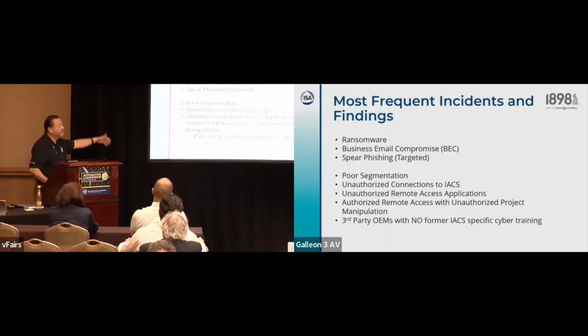So other pieces here, I think we talked about poor segmentation, unauthorized connections, we see that a lot, unauthorized remote access applications. The TeamViewers, the RealVNCs, the UltraVNCs, the RAdmin, there are so many remote access tools. It's dumbfounding. And we see that a lot as beacons, even offshore and even in the onshore circuit. And then third-party OEMs with no formal cybersecurity training on the actual systems that they're working on.